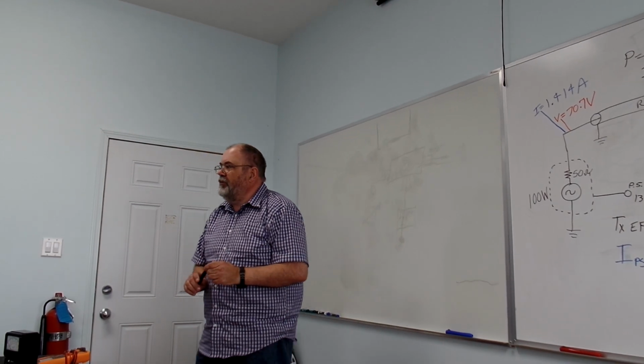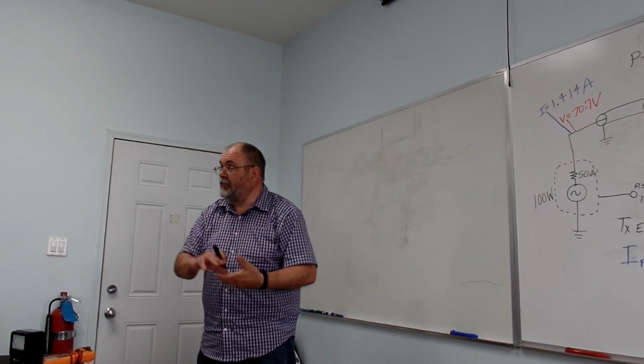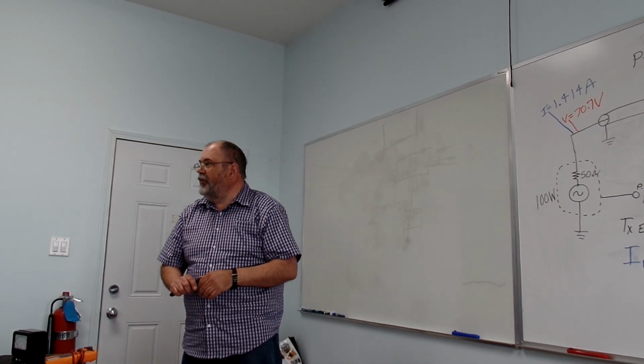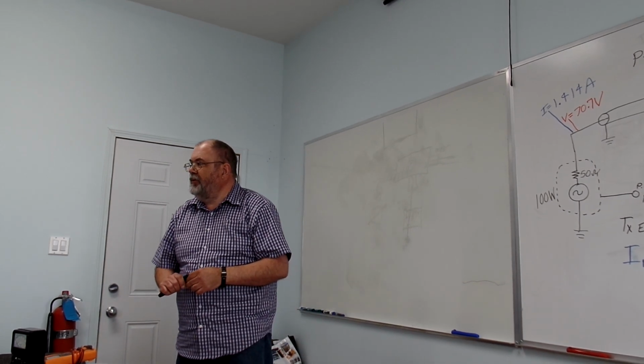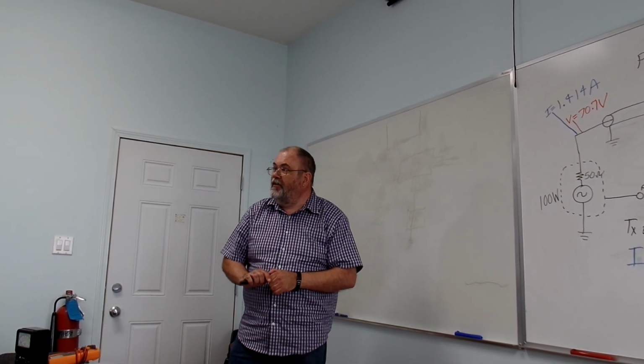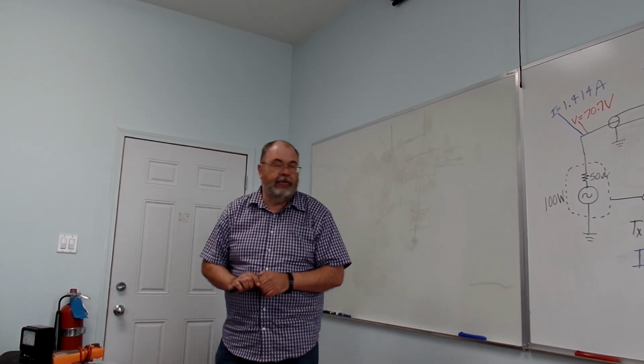So our transmitter is starting to get hot. And if it's a modern transmitter, it'll have temperature sensors and SWR sensors, and it'll automatically turn its power down to avoid burning itself up. If it's a Chinese-made one, good luck. Hopefully you've got big cooling fans and bags of ice.